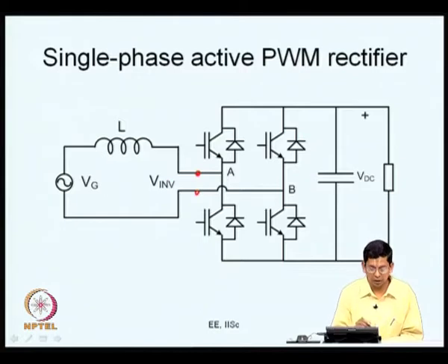So, this is realized by using a voltage source converter like this. Use this voltage source converter to apply the desired V inverter, so that you get your I of required amplitude and in phase with the voltage. This presumes that this capacitance is charged and the voltage is maintained at VDC. Obviously, such a converter requires closed loop operation, and the inner loop will be the current control loop, and the outer loop will be the voltage control loop. Once again, the control of such converters will be dealt with in greater detail in other NPTEL courses on power electronics.